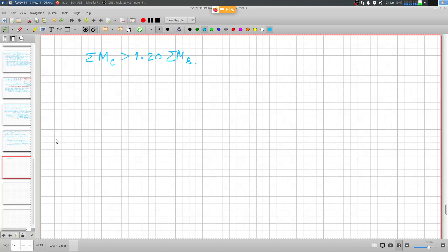That's what is recommended in the IS code, and when we say this sigma MB, obviously it has to account for the overstrength of the beam moments, just to be on the safer side, because absolutely it is not possible to tolerate any kind of hinging developing in the mid-story columns. Plastic hinges at the support,